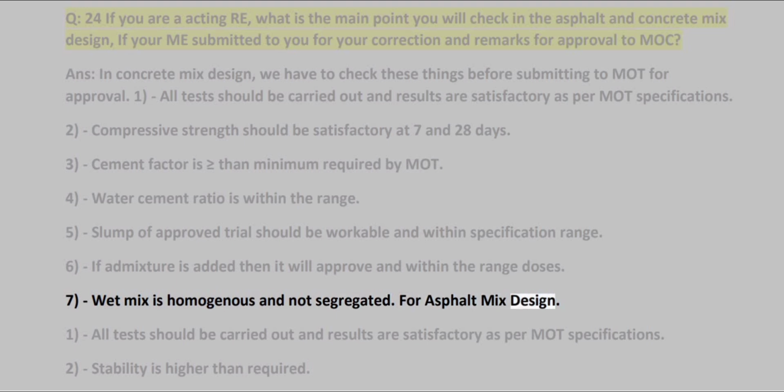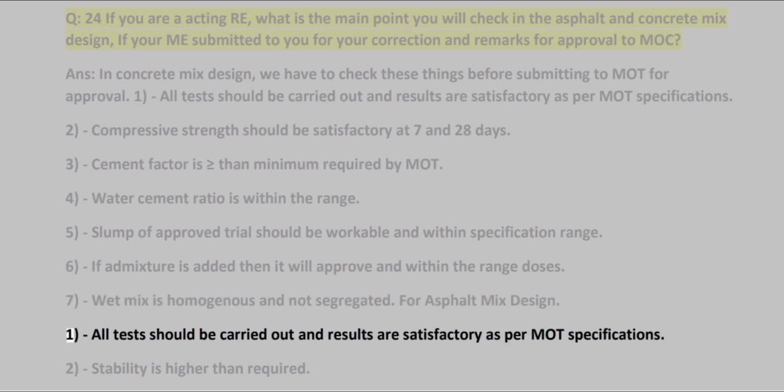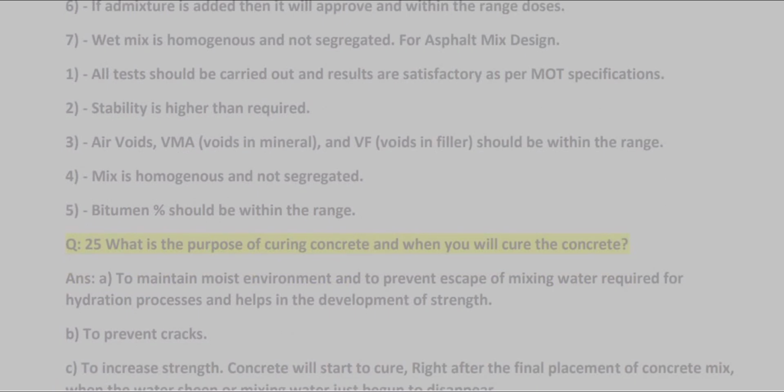For asphalt mix design: 1. All tests should be carried out and results are satisfactory as per MOT specifications. 2. Stability is higher than required. 3. Air voids, VMA, voids in mineral aggregate, and VFA, voids filled with asphalt, should be within the range. 4. Mix is homogeneous and not segregated. 5. Bitumen percent should be within the range.